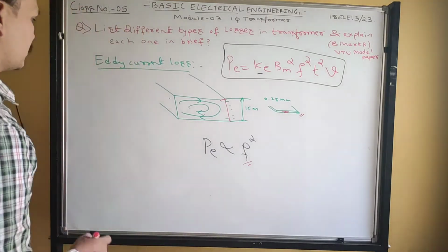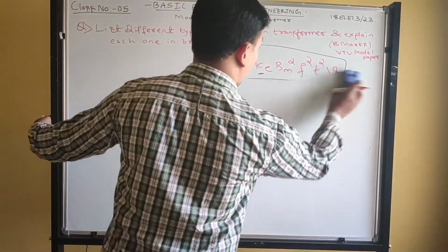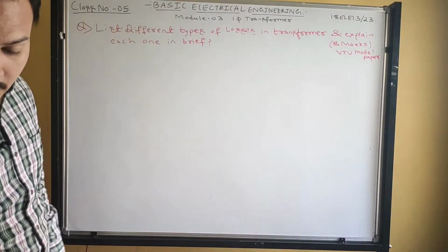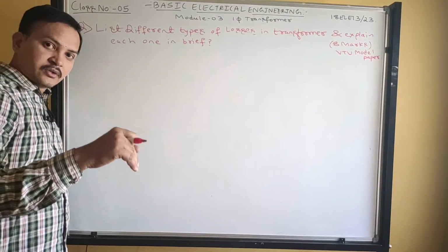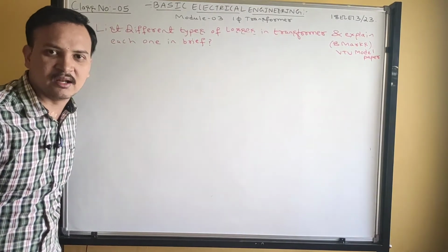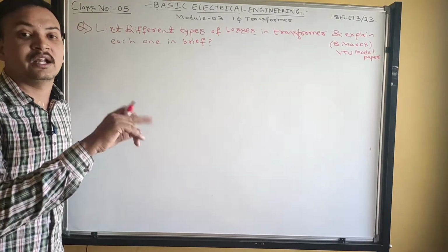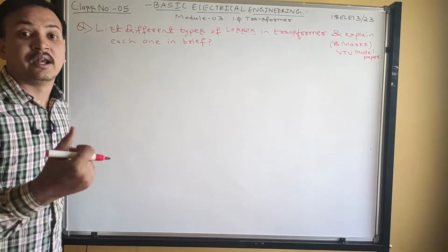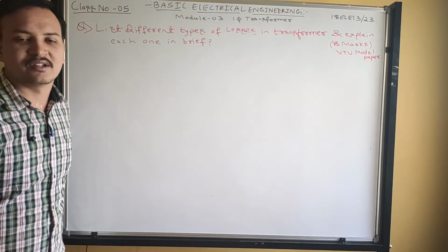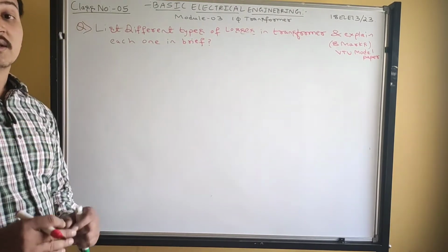Okay, got it? So, summary. Guys, pause the video and copy it out. What can you write as the definition for hysteresis loss? When an alternating current flows through the winding, the core undergoes a cyclic process of magnetization and demagnetization. During magnetization, energy is stored. During demagnetization, energy is released. The difference in the energy produces a net power loss. This power loss, which heats the core, is called hysteresis loss. We can understand hysteresis loss better by plotting the BH curve.